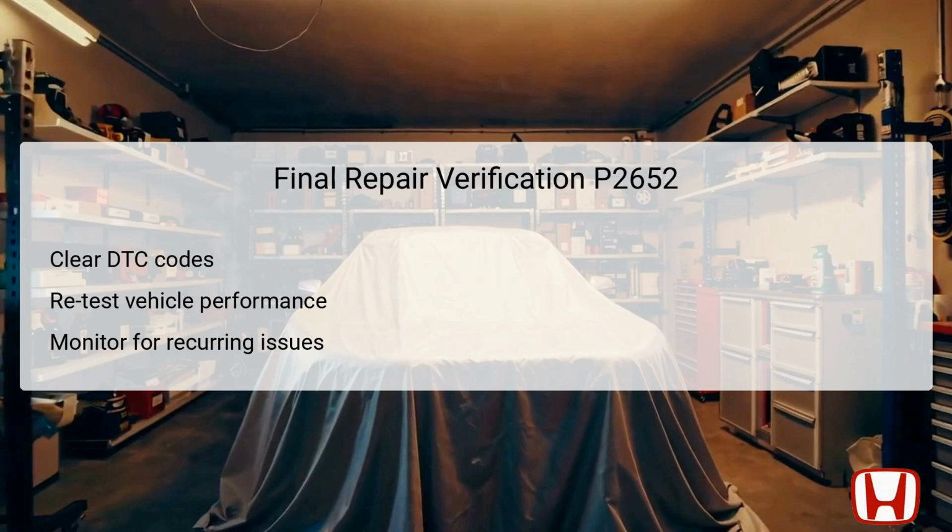It is crucial to observe the vehicle's performance post-repair during various driving conditions to ensure that no related issues return. Monitoring the engine function and the consistent operation of the rocker arm oil system will confirm the efficacy of the repair. Should DTC P2652 reappear, further inspection and diagnostic procedures must be resumed.